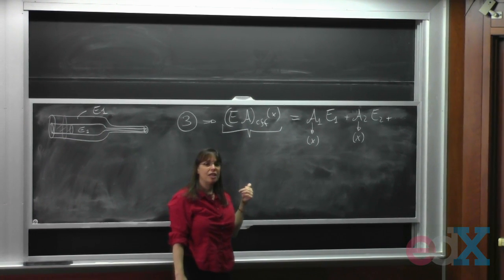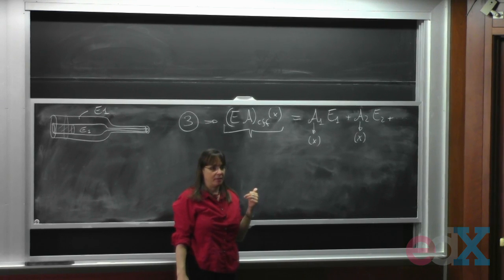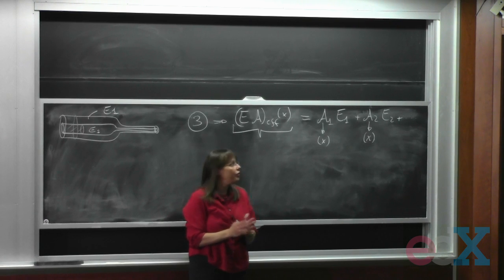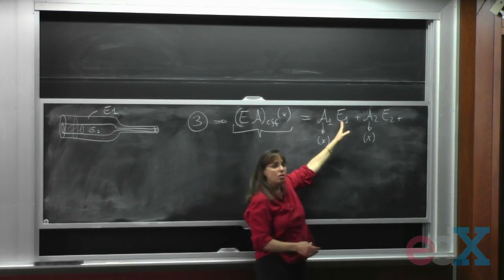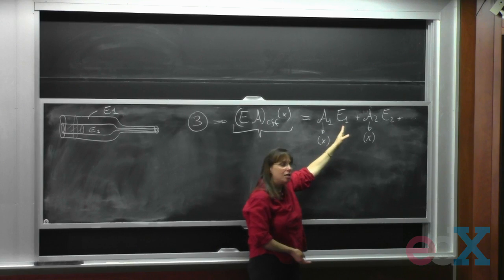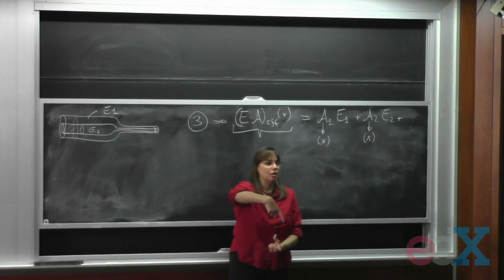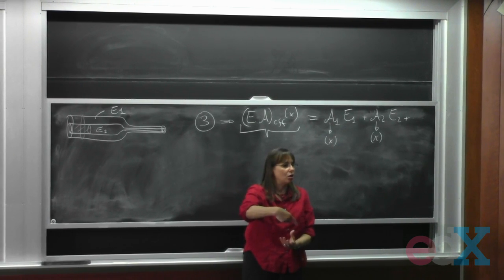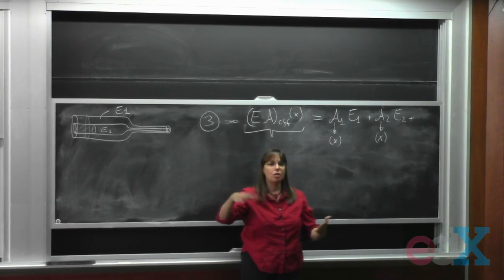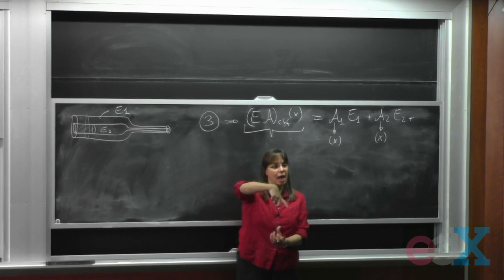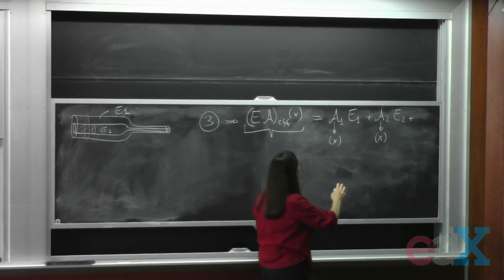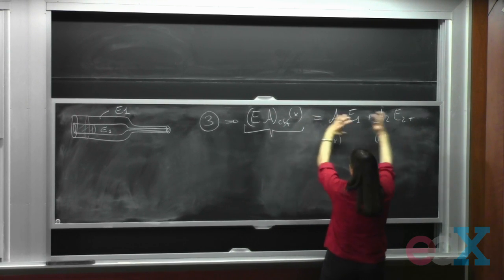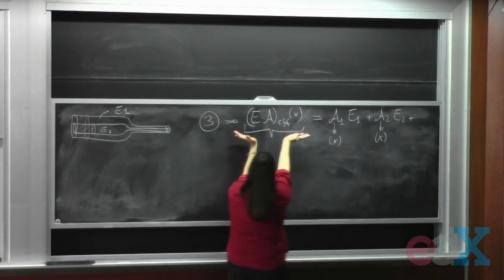The effective section stiffness. This tells you how stiff the section is. Something is very stiff if it has a high modulus, a high Young's modulus, and if it is big. Something stiff takes a lot of load to deform, right? So something which has a high modulus is stiff. Something which has a high cross-section is stiff. All this information, the section, geometry, and the material, they get put together into this guy over here.